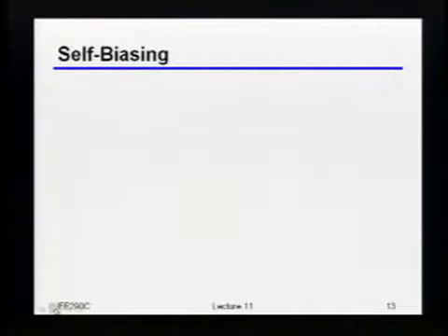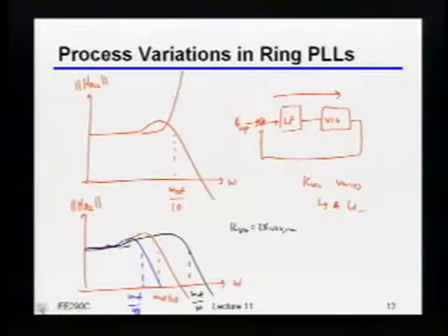I just got an additional question about this K for the digital VCO. I remember someone told me it's really not linear, right? Does that actually have any kind of implication? Yes and no. In this particular context of setting the loop bandwidth, I'm saying that the linearized KVCO could be moving.